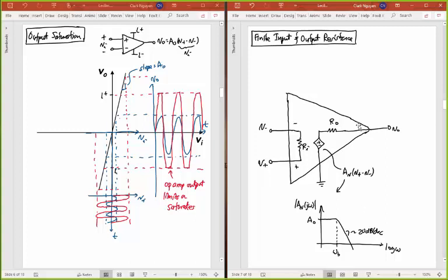But this circuit that I'm showing right now does not reflect this transfer function because somehow I have to stick this omega b in. I have to stick the pole in. Okay? The best way to stick the pole in an ideal op-amp type circuit is just to stick a capacitor in a certain spot. And where I like to stick the capacitor is right here.